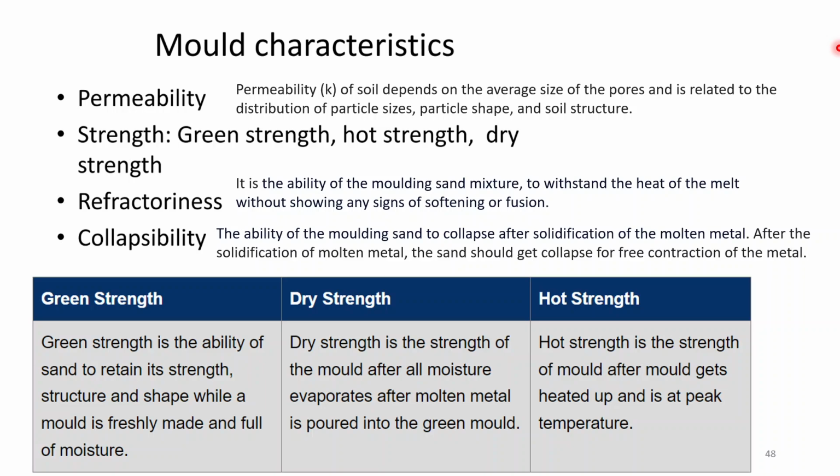So permeability comes into the picture when you see what will be the final porosity in your mold, right? If it is not nicely permeable sand, then the gases will get entrapped and they will act as porosity in your casting.